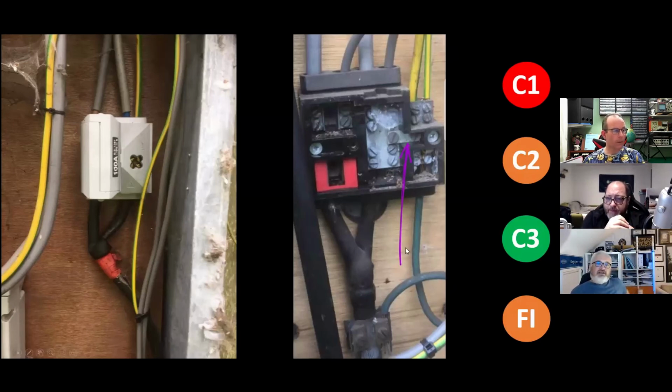But I've seen, Dave, separate earth wires that have come in literally separately all the way along and into that side connection. I've also seen inside these, when I've done new meter connections and renewed all the tails, where that link isn't in. And that's the fascinating part about these intakes and this whole DNO mystery: how much do we actually know about the supply configuration that's coming in? Because the theory of what we should see.